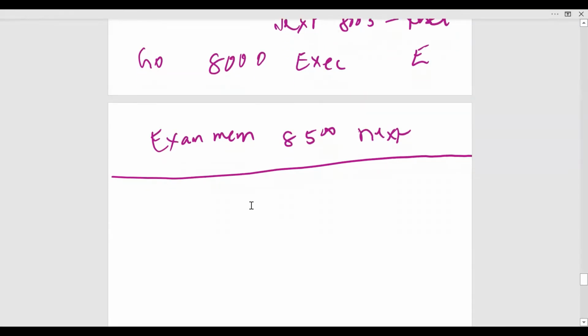The next program is another simple program. So we have seen two instructions, that is how to move the data to the accumulator and how to store the data from accumulator to memory location. Now I'll use one more instruction called complement the contents of accumulator. That means I'll take some data and complement it and store the result in a memory location. So let us start the program.